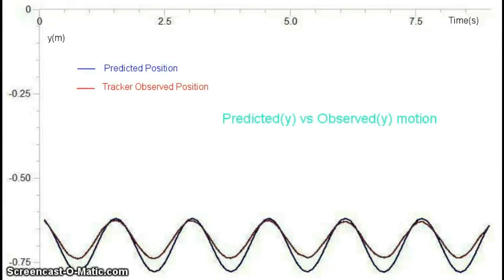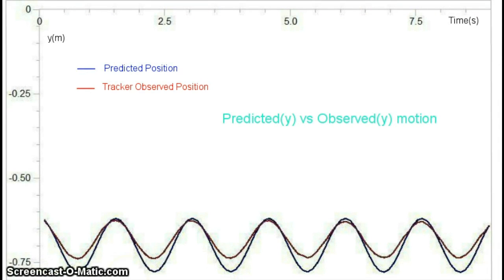The resulting display window shows the difference in Y coordinate and the observed tracker data. Of concern is the difference at the minimum end of Y coordinate. This is as much as 5 centimeters out. Perhaps my tracker observations were not accurately made, or the origin was misplaced.